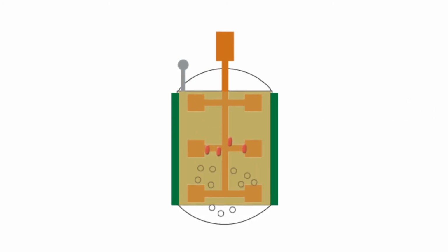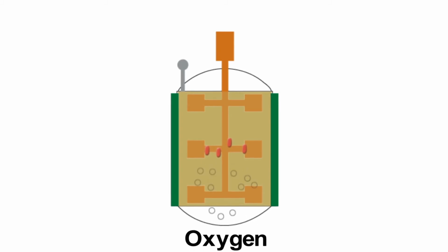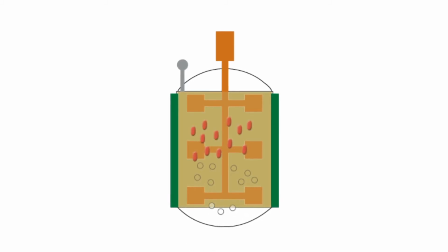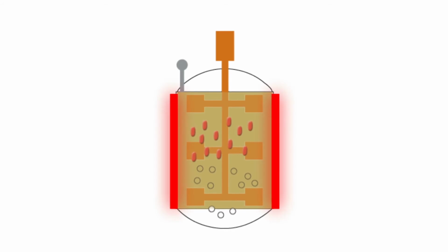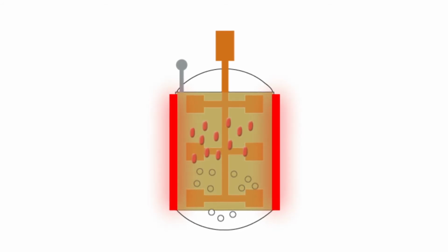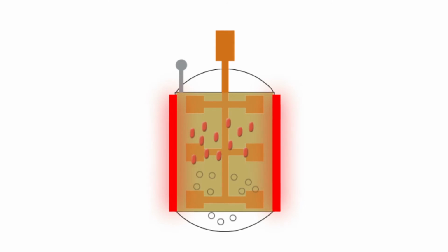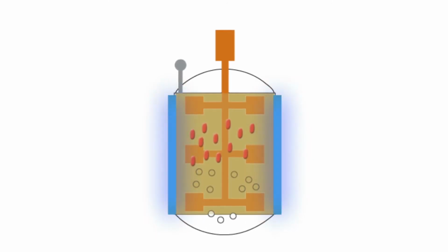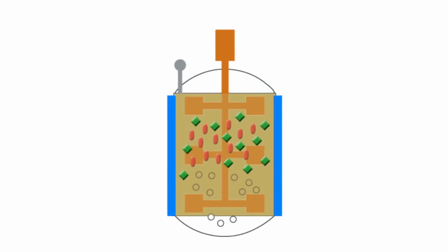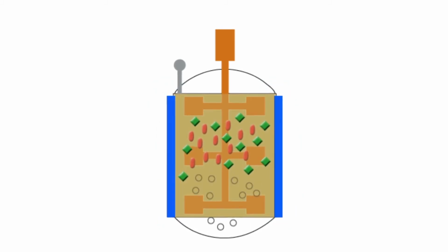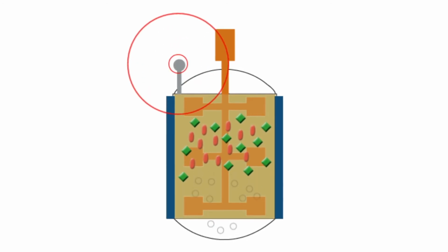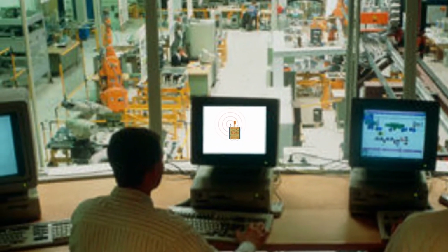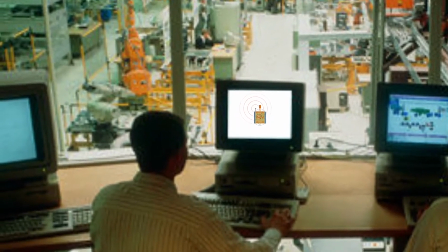Oxygenation. The amount of dissolved oxygen available to the BT organism as they grow and multiply has a profound impact on toxin, protein, and spore development. Cooling. Fermentation is a heat-generating process, and cooling is required to maintain an optimal temperature for maximizing toxin protein development. Process monitoring and quality control. Just as knowledge and experience with BT fermentation greatly impacts each manufacturer's process, in-process monitoring and adjustment of all these parameters is critical to success.